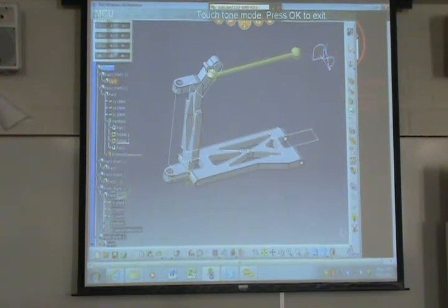You'll notice here that my pin isn't quite constrained correctly, and so technically that pin should be located inside this little segment here, and then my control arm is constrained to be on top of that little pin, so it looks like the pin's just not updating. But I can do that.